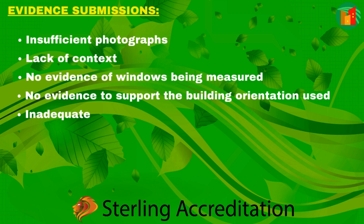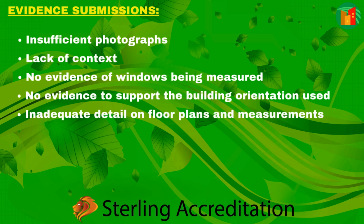Inadequate detail on floor plans and measurements. Floor plans do not need to be of marketing standard, but they need to clearly show the layout of the property and location of key features. Conventions 2.01, 2.02 and 2.18 apply to the measuring of properties. It must be explicitly stated whether measurements are taken internally or externally. All measurements, including windows, must be to 0.01 meter or better. Assessors must clearly show the measurements they have taken on the floor plan and should also supply clear calculations to show how they arrived at the inputs used in the assessment.